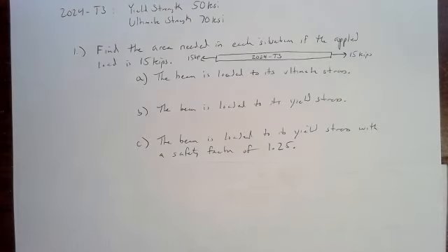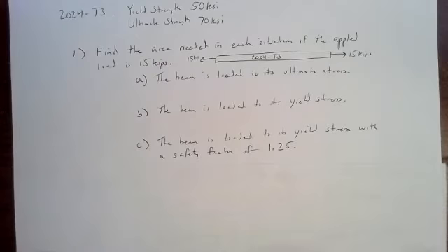So since in the lecture I applied the safety factor to the load, I think here we'll apply it to the yield strength. Remember the fundamental application of the safety factor: it multiplies the load, but it divides the strength. We assume the material is either weaker than it actually is, or we assume the load is bigger than it actually is. So this time I'll correct my stress.